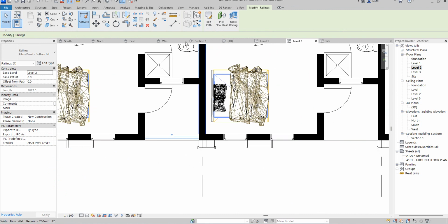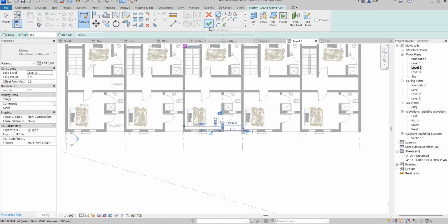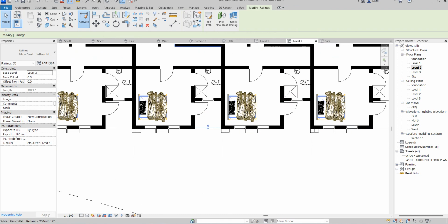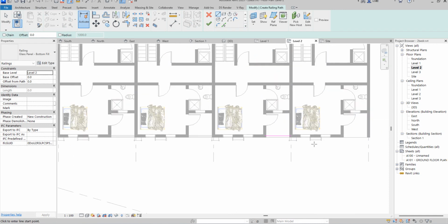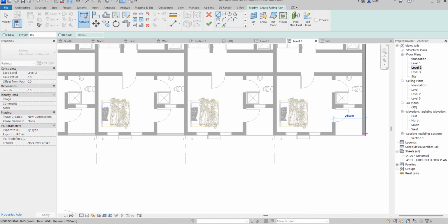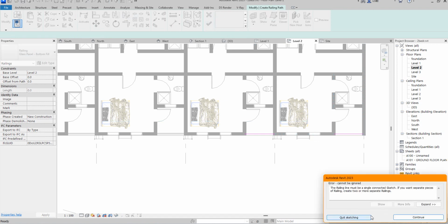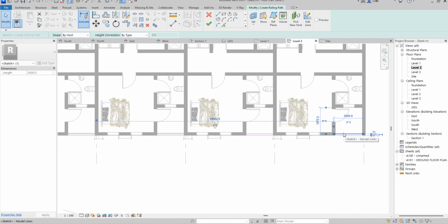So I've got to go on and create similar ones. You can decide to copy if you have created one and start copying them from one point to another. You see, it is the same way, but the only thing is that you cannot draw two lines like this together. It's going to have issues. You can imagine what we see here now. You see that there is a script error, so just quit or continue whatsoever. Delete one of them.